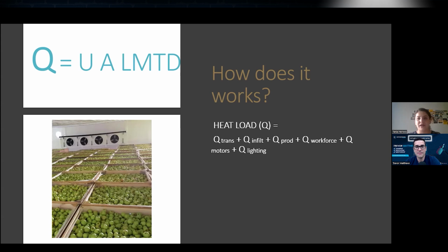And for a condenser or a gas cooler, the heat load considers the heat absorbed in all of the evaporators of your installation, plus part of the heat generated in the compression process. Me, as a heat exchanger manufacturer, I'm not involved in this part. It's the contractors' job to do all this calculation. They only tell me, I need this evaporator for 10 tons of refrigeration, or I need this gas cooler of 12 MW of capacity. Yep.